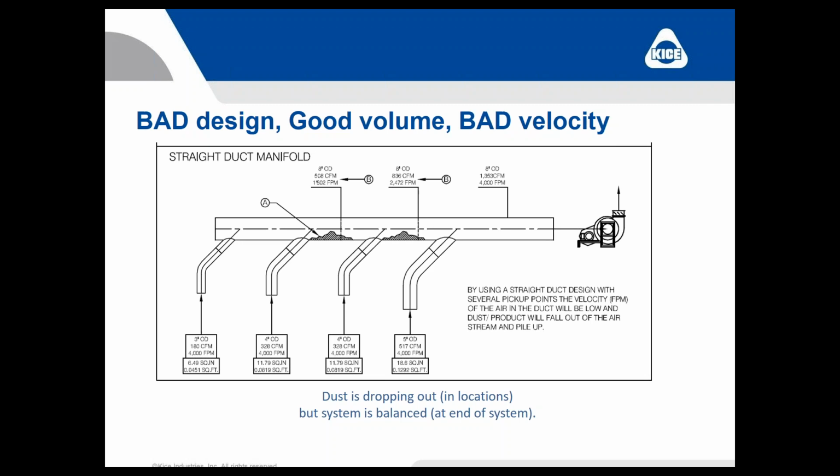And then they branched off with that. Well, in this case, that area of an 8-inch tube is not going to have very high velocity when you don't have very much airflow. Again, going left to right, I've got that 3-inch tube at the very end. It's only 180 CFM. Even after I pick up the 4-inch tube, and now I have a sum total of 180 plus 328, call it 508 CFM, my velocity in that 8-inch tube is only 1,500 feet per minute.